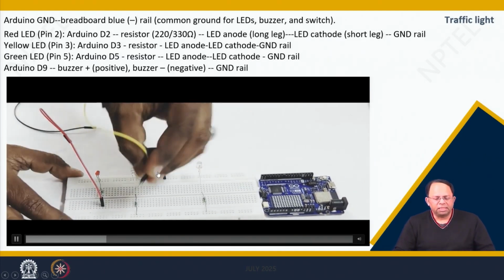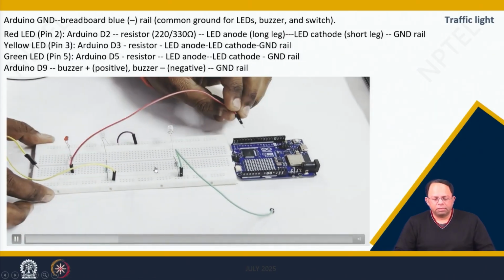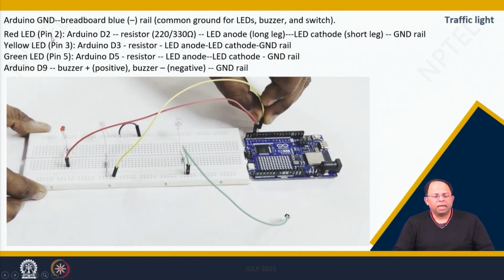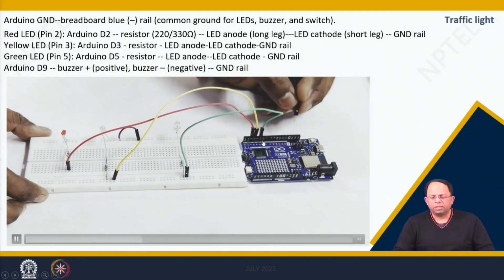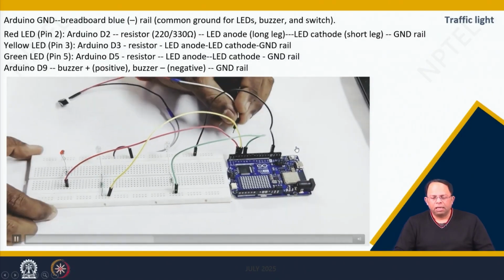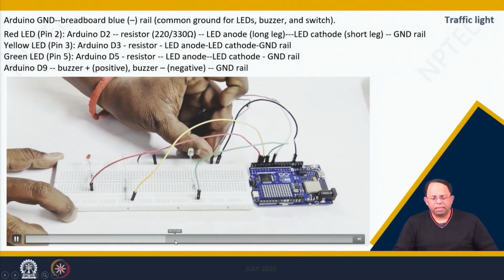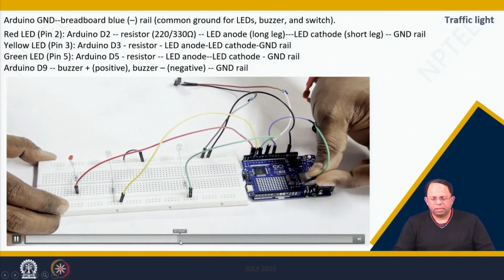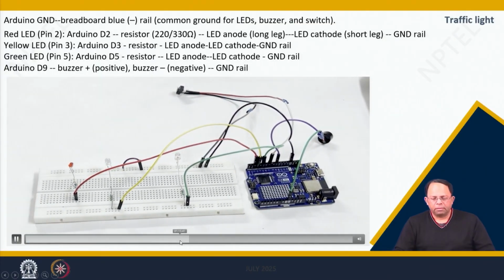Once it is connected, we can now connect the different pins to the different pins of the microcontroller as per the different resistors as given over here. We are connecting from the resistor to Arduino D2 or D3 or D5 as per the requirement, and this is the jumper wire, so we can connect very easily, and once it is done, automatically our circuit starts. And we can also monitor that in the serial monitor as well. Once the connections are all done, as you can see the ground pin is getting connected, I guess. Yeah. And now we are ready.